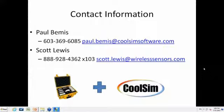Let me point out that optimizing your data center for cooling can save a tremendous amount of energy. And remember that for every dollar you put into the data center to drive the IT equipment, you're spending another dollar to get that heat out of the room. Every kilowatt that goes into that room, whether as fan energy or IT load, turns into heat and has to be pumped back out or dumped somehow.